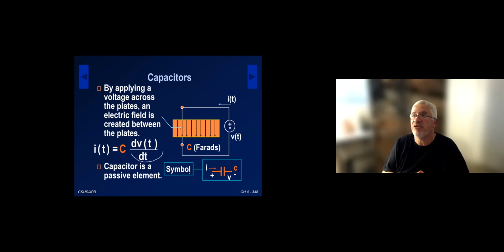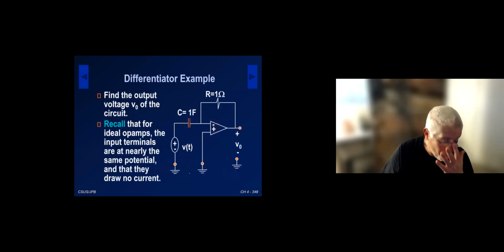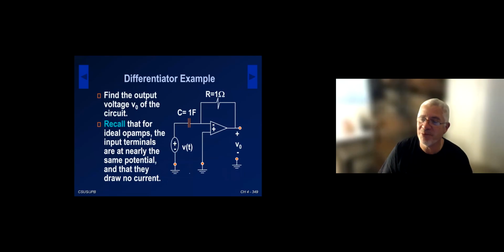That's what I'm saying. The voltage current relationship, or in this case, the current voltage relationship for the capacitor, is really based on the way the capacitor is constructed. Okay, the current is proportional to the time derivative of the voltage, and that constant of proportionality is the capacitance in farads. All right, and I'm showing you the electric symbol we'll be using for the capacitor, following the passive sign convention. So again, I'm showing you some basic examples.